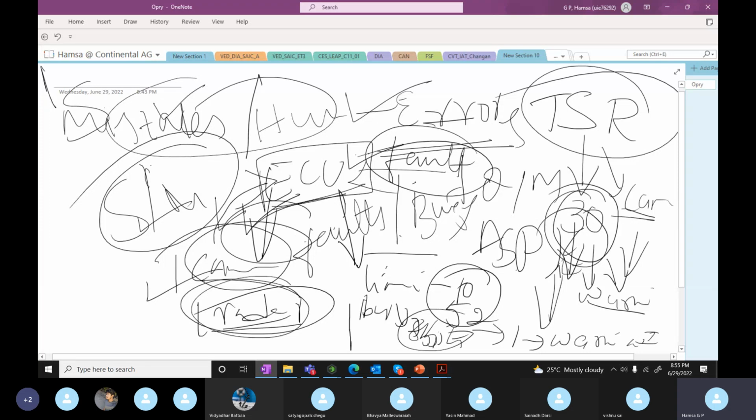These types of faults will always have bit 7 set high, meaning the warning indicator should be turned on for these faults. Whenever this fault is set in the ECU, it will start beeping, warning the driver that something is wrong with the camera or the radar, that the ECU is unable to get the input from the camera or radar. Understood?